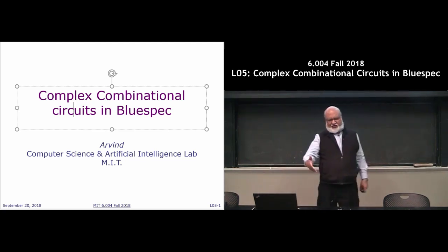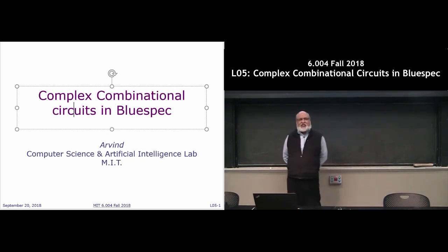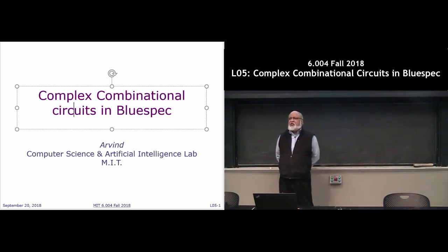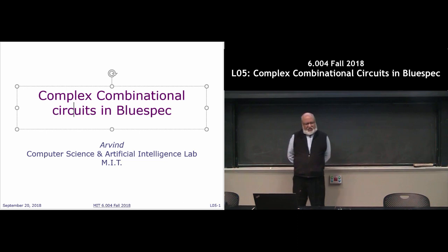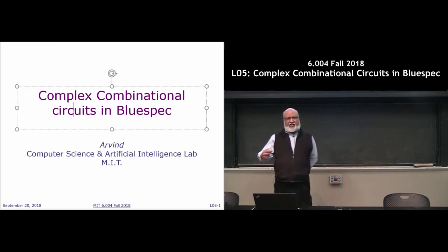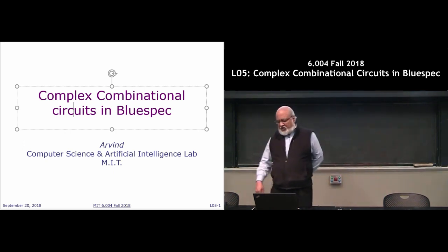I've just written the same thing here in a more compressed form so that I have space. Another way for me to draw this would be that the unfolded loop defines an acyclic wiring diagram. This is what you saw: the full adder has x0, y0 going into it, and you're feeding the carry in and carry out from it, and every stage produces a sum bit also.